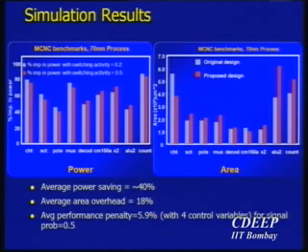But I'm talking about completely asynchronous. One of the points is, how do I know when I've completed? So I need some sort of dual rail logic, right? And that's a traditional problem. Once you bring that in, some of your advantages can go away. So what we did in that particular case is that we actually had replica circuits, and based on the replica circuit, we determined that the operation is complete. So not fully asynchronous, but leakage was playing a major role in that case, or power consumption.